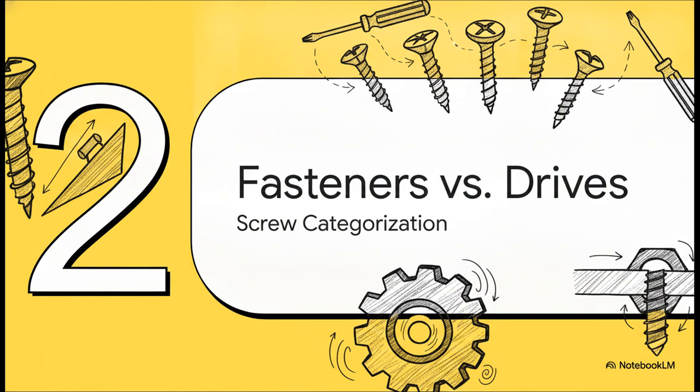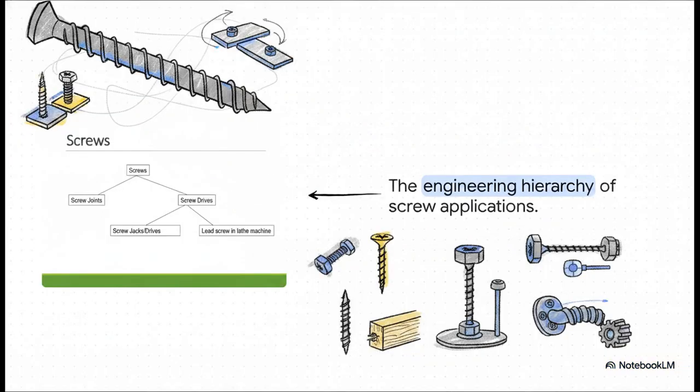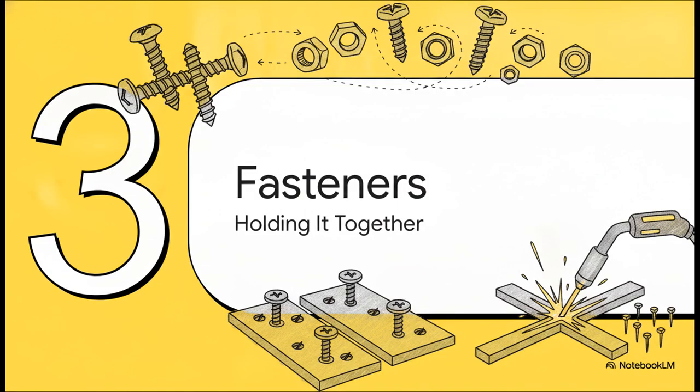Fasteners versus drives. Knowing that a screw is essentially just a wrapped ramp, let's look at how engineers actually apply it. In the engineering hierarchy, screw applications branch off into two very distinct paths. You've got screw joints, which we usually call fasteners, and screw drives. Fasteners are designed strictly to securely hold things together, while drives are engineered to create deliberate, controlled motion. Let's head down that first path, fasteners, and how they hold things together.